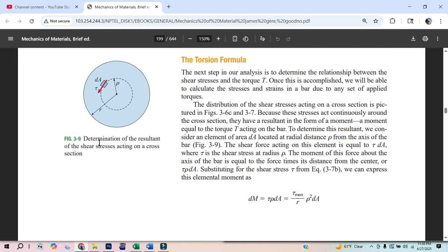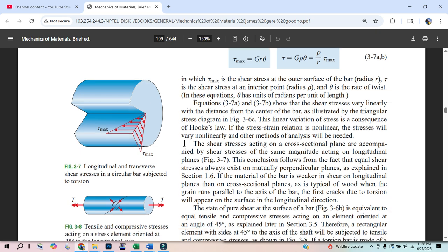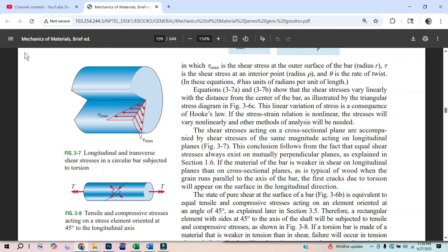And then what we have to understand is that force is a distance away from the center, and that's providing a torque. And why is it providing a torque? Because we welded this ring to the wall, and then we're torquing this ring downward, and the system is balanced from statics. So there must be an equal and opposite torque the other direction, and that's being provided by the internal reactions. So if I drew a slice right here, and I said this slice is torquing down,